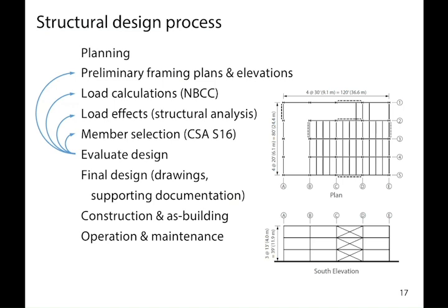But we can't forget about a very important part, which is people have to use this building every day. People have to maintain this building every day. So even after the building's constructed and it's occupied for the first time, engineers are still thinking about, okay, is it comfortable? Are the floors too bouncy? Are the braces shaking too much? Is there too much noise? Is the wind blowing the building so much that people are uncomfortable? And did I select materials that are durable enough so that this building is going to perform as intended for its 50-year lifespan? Okay, so those are the things that we think about throughout the structural design process. So the structural engineers are primarily engaged in this stage, but they're stakeholders in the long-term performance of that building as well.